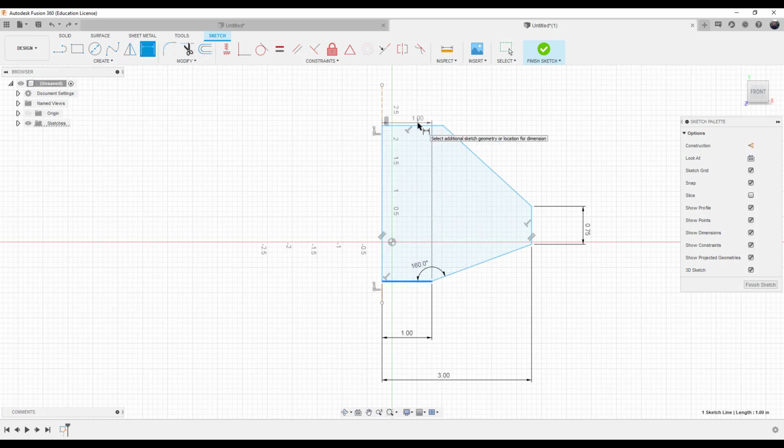We're going to go ahead and do a dimension overall. Sometimes it doesn't always work exactly the way we'd like. We'll do this as 3 inches, and the dimension angle from here to there. Okay, remember, opposite angles are exactly the same. We're going to set this at 135. And so we've got an interesting shape, to say the least. Even though it's not directly in the center line, we'll be okay.